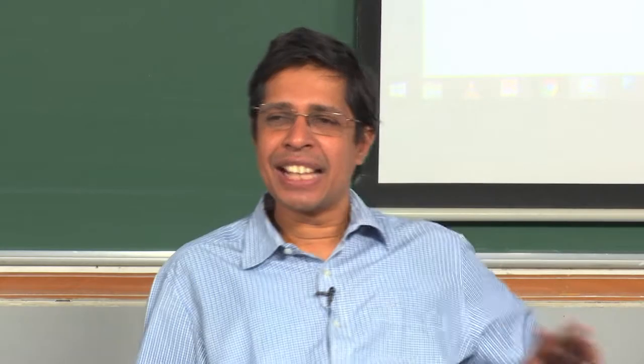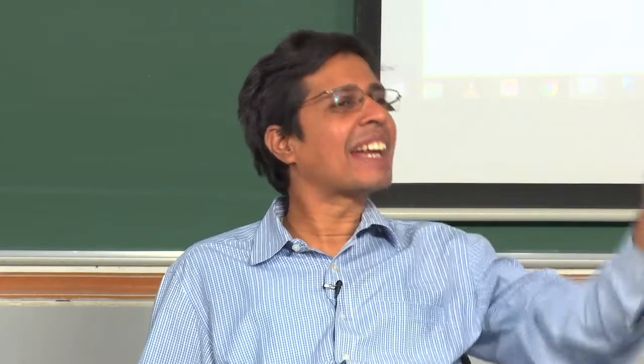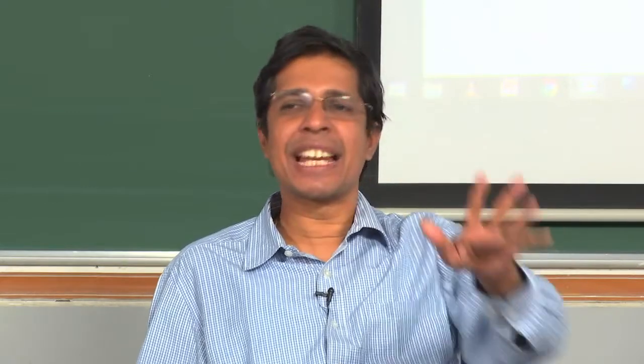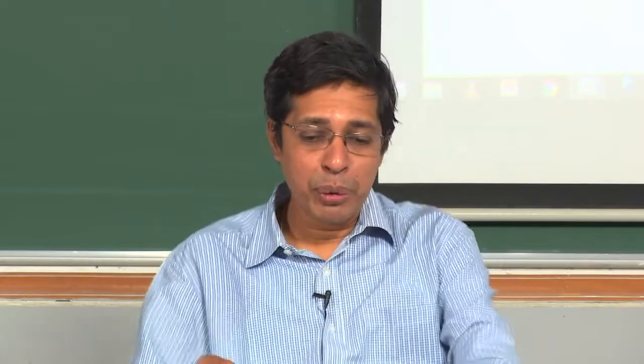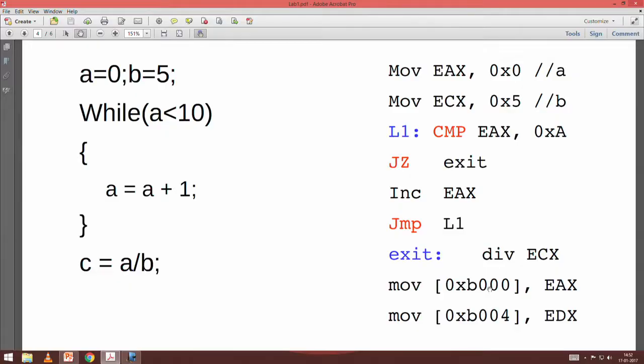So this memory addressing is a memory direct addressing, because I give the address directly there. To which memory location should I write? I say 0xb1000, I give the address directly, and I put those square brackets, which is very important, which says that I am writing into that memory, right. So this is called memory direct addressing.